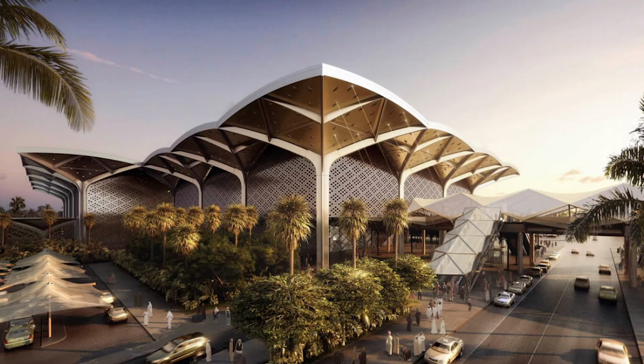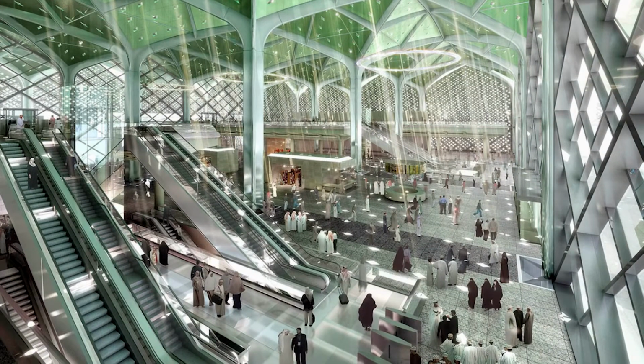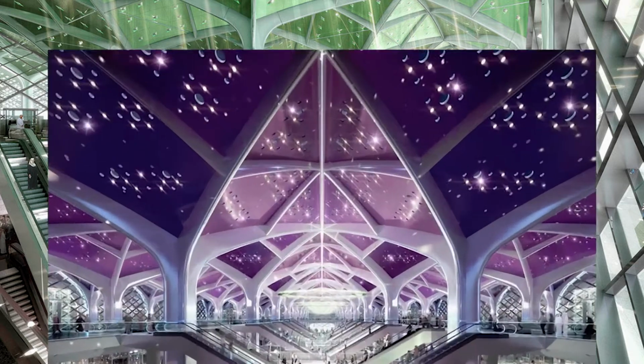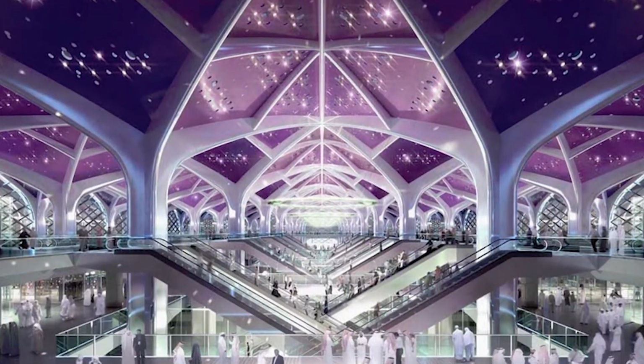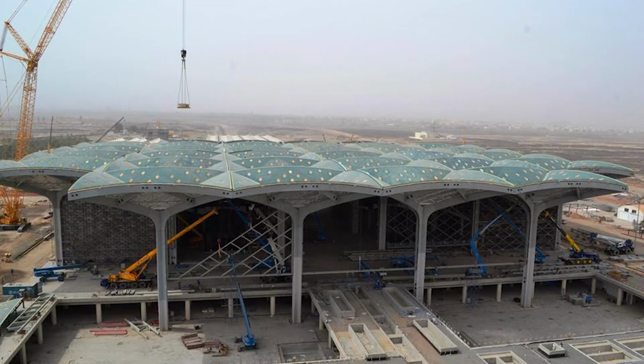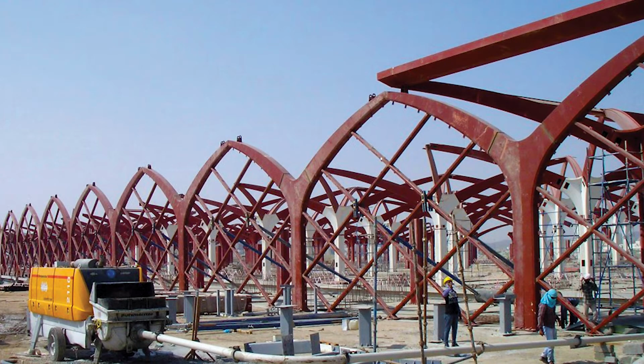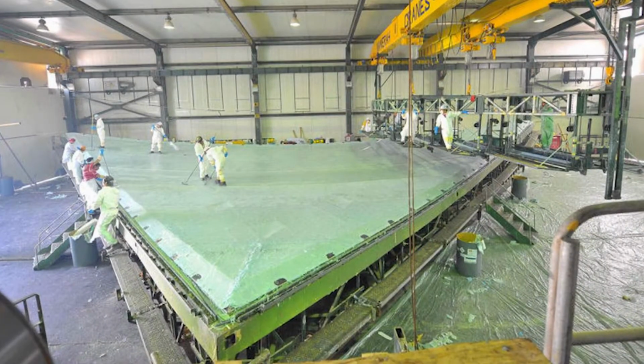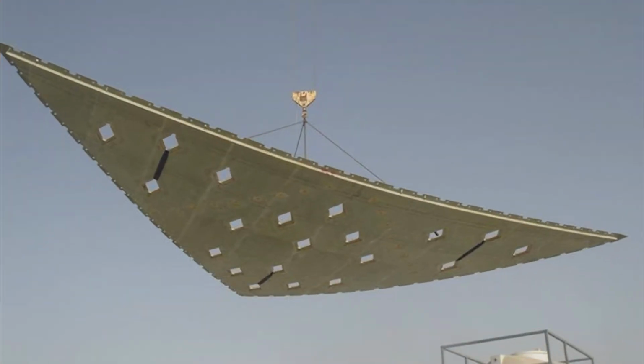What is perhaps the world's largest FRP construction project is currently underway in Saudi Arabia. The Haramain Railway Station project consists of 5 stations for a 279-mile high-speed railway system. Designed by Foster & Partners, the project consists of structural steel columns supporting an FRP roof system fabricated from large composite panels. These are sandwich panels composed of a fire-retardant foam core enclosed within an FRP shell.